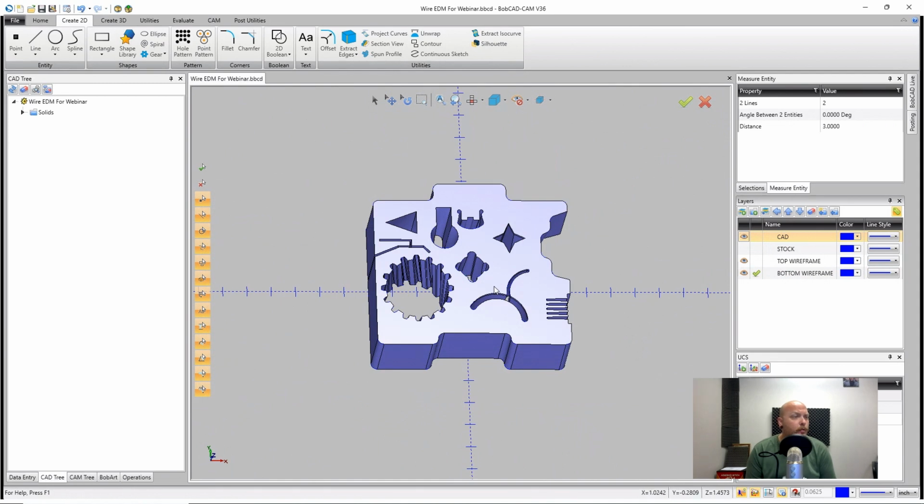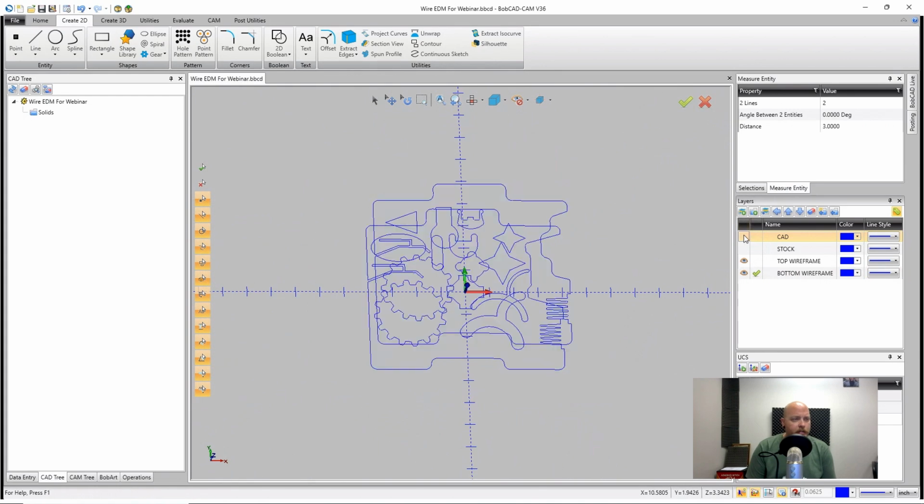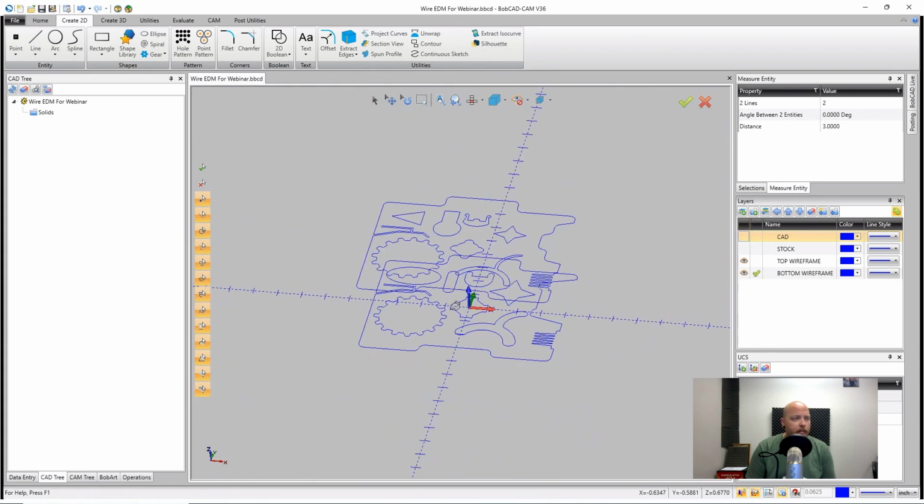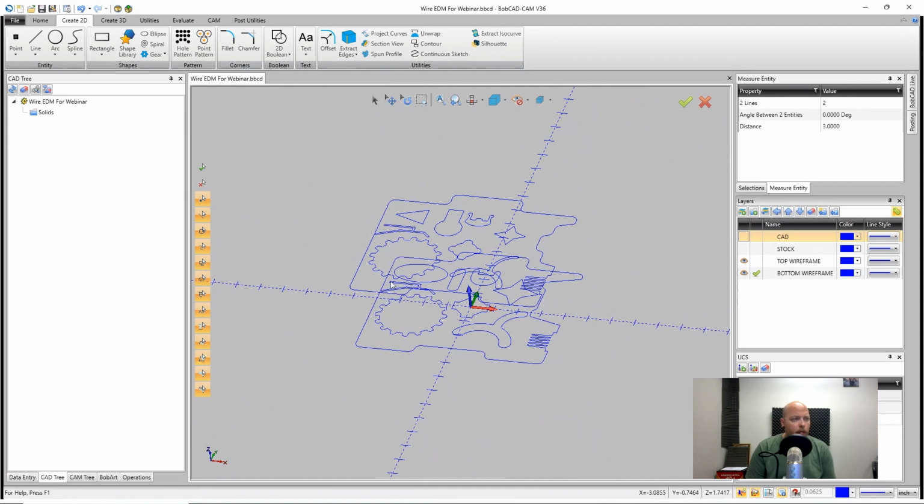And you could do a standard taper with a 4-axis. You just have to have both shapes instead of just letting the wire do it itself. Now, you couldn't do a land and a taper doing 4th axis because it's going to have whatever the shape difference is. It needs to know to do a straight cut and a taper cut. And the regular feature, the 2-axis feature, will do that. So the geometry, once again, you're just going to extract the edges and kind of leave it where it is. All right, we'll talk more about getting some other edges that we may need later on.